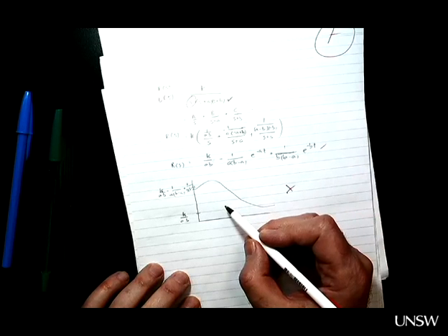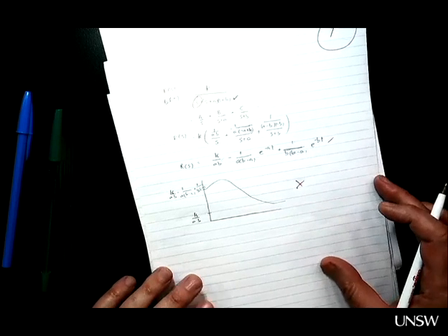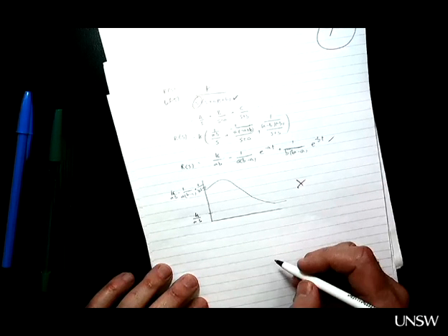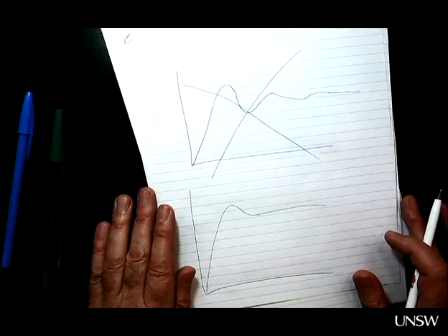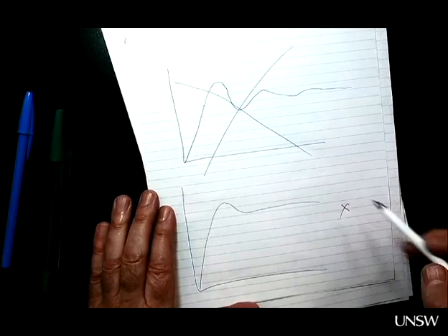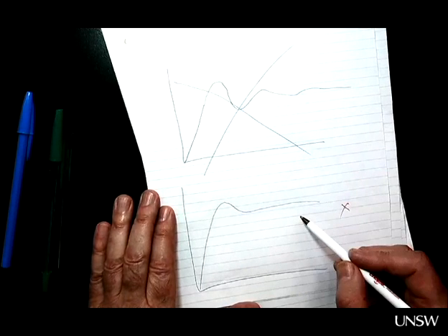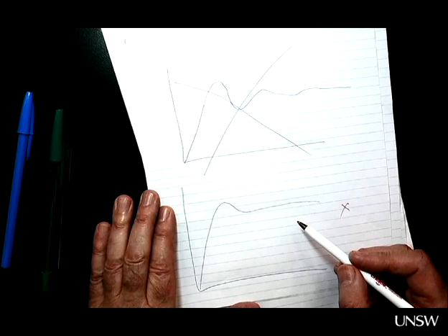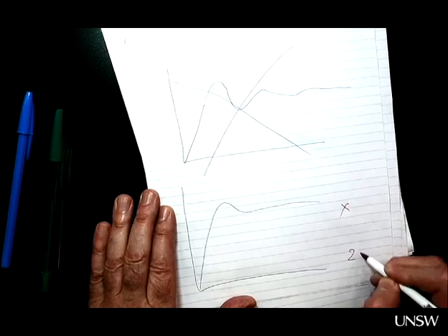So experts, what do you say out of 10? 6? 6, okay. So that's front. The rear, actually, this is a very good sketch of an underdamped system. But it's not overdamped, okay. They did try. Okay, they reduced the overshoot, they reduced the ripple, they shortened the settling time, so it's not that bad, but actually the answer is wrong. So 2 marks for improvement. Okay, this was really wrong, this is a bit better. 2 marks.